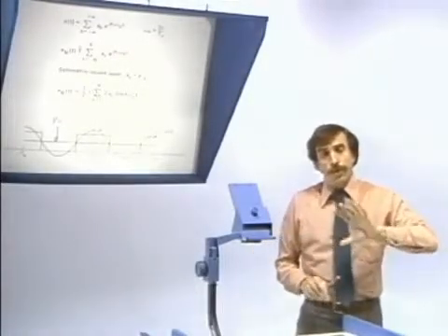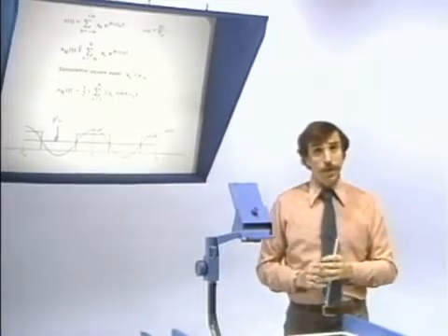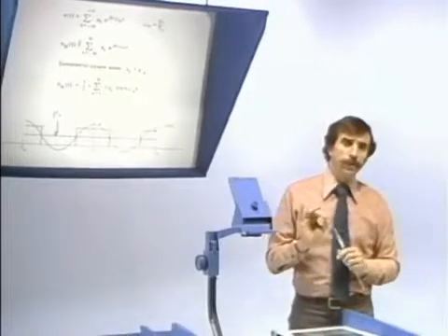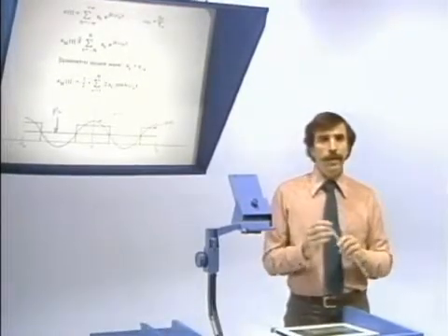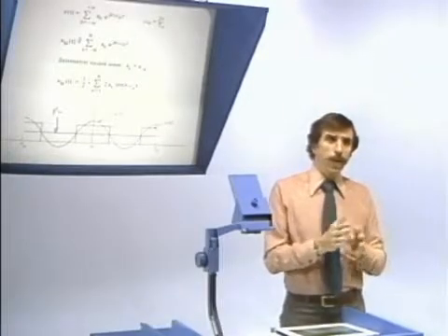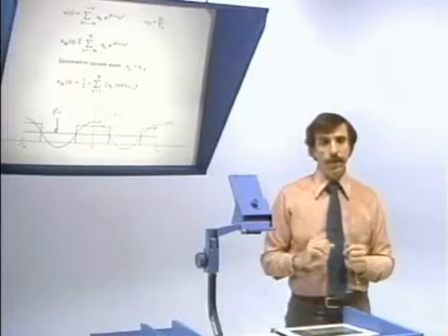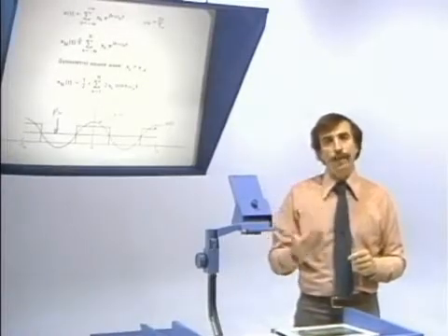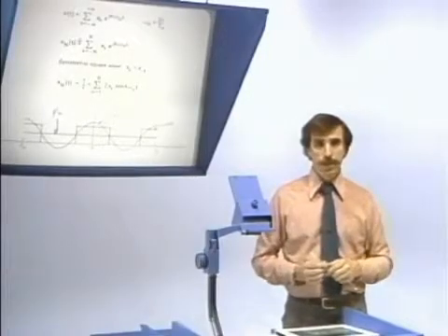Okay, so what you saw is that, in fact, we got awfully close to a square wave. And the other thing that was kind of interesting about it as it went along was the fact that with the low frequencies, what we were tending to build was the general behavior. And as the higher frequencies came in, that tended to contribute to the discontinuities.